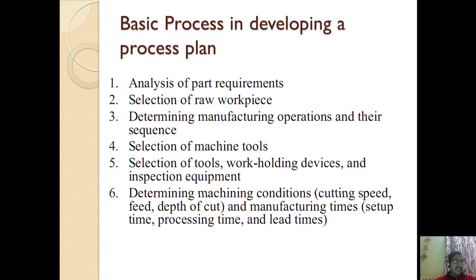So basically, what are the activities? Again, I will recap once again: study of the overall shape of the part. First you have to classify the part, what type of part it is, cylindrical or non-cylindrical, its detailed dimensions, and then determine the workstations required, and then analyze the part requirements, part surface requirements, tolerance, surface finish. You have to decide which is the cutting tool for the machining condition, and select the raw material and base shape